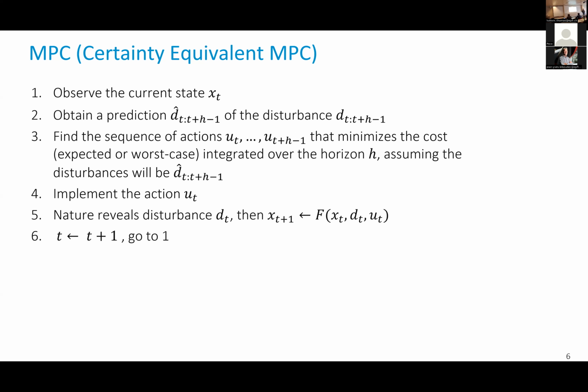But how much do we need to heat up? How will we increase the temperature? By how much do we increase the temperature? This we need to compute. There might be times also where we do need to heat because the temperature is dropping and we have a choice to make. Should we heat now because the temperature is dropping a bit, or should we wait a bit and heat in 5 minutes when the electricity will be much cheaper? So those are the things that we may need to take into account. So we want to have a look at the future, at the entire trajectory, and decide what to do now by having a prediction of the future.